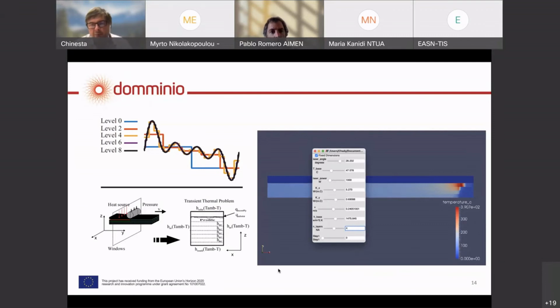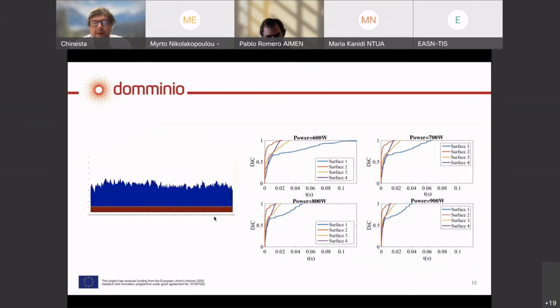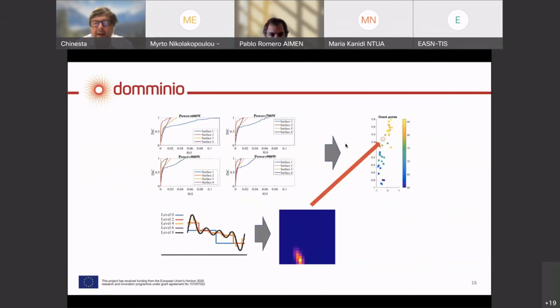So this is almost ready, and it takes into account all the standard process parameters and the reality that is the contact between, or the rough surface between the tape that we are laying and the previous one that I introduced in the laminate. As soon as this is ready, we can simulate the consolidation, we can evaluate the evolution of the degree of intimate contact, and depending on the process parameters, I can evaluate the evolution of this intimate contact. And now by using machine learning, the idea is to correlate these